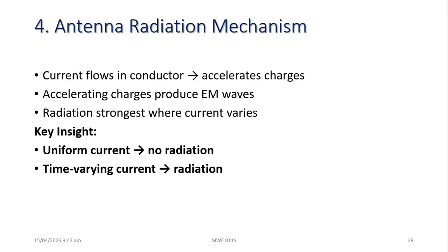But the moment you have oscillations at a given frequency, the electrical signal must be oscillating at a very, very high frequency for you to have the strongest radiation. It must be time-varying current, which means it must be oscillating. The key thing to take note of is that if you are injecting DC towards your antenna, you get zero radiation.